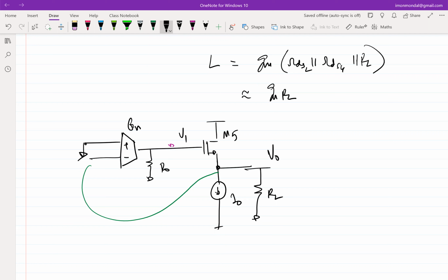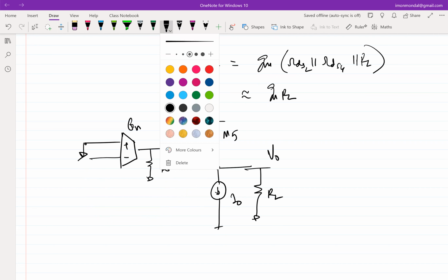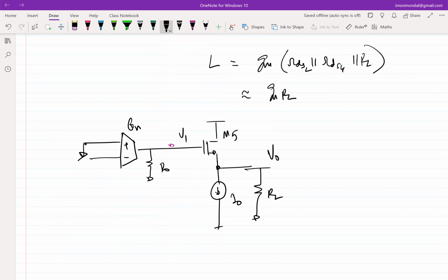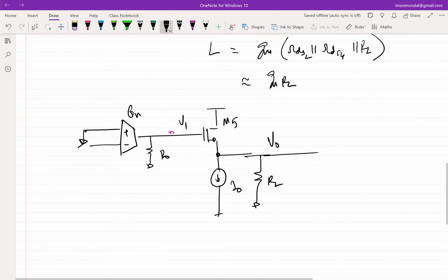Yeah, but what is the output that we want? We want V0. So you are saying that I have to do this, right? K minus 1 R, and then connect it. So this feedback will work, but will the V0 be equal to K times Vi? No, not exactly, right? So what you suggested is actually used in some places. So I'll come to that. But if we have to draw a parallel between whatever we were doing earlier and now, this is what we want.